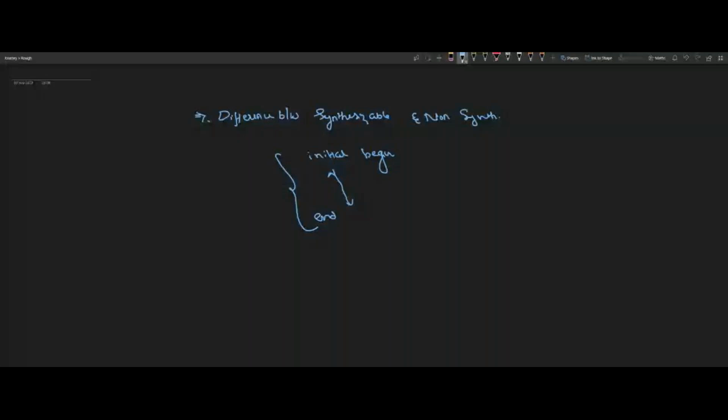But for example, if you want to implement that 10 millisecond delay inside the FPGA, how do you do it? These are the frequent questions, and that way we frame the consecutive questions. We will ask which are synthesizable, and they will say that delay 10 millisecond is non-synthesizable. But in FPGA, we may need that delay, right? So if I want a 10 millisecond delay, can you tell me how you are going to achieve that?